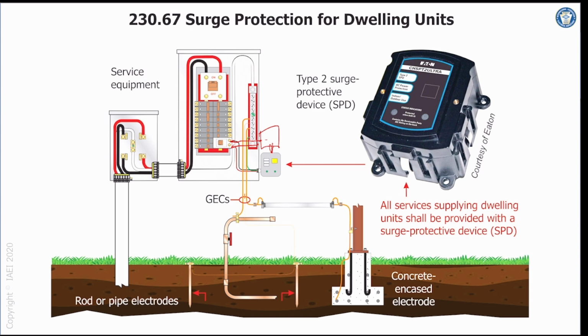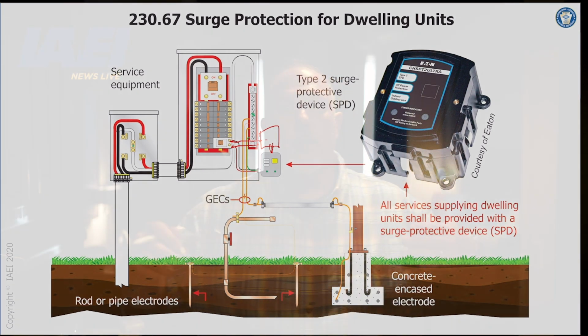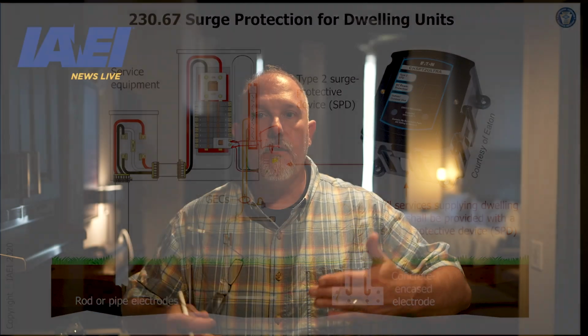Remember that the longer the lead length, the more voltage you let through on a surge. If that conductor lead length is long enough, that surge protective device does nothing for you. So it's a very important, critical piece of the puzzle. How short? Keeping those conductors short and straight. Integrating that surge right on the bus is the best solution you could possibly do.